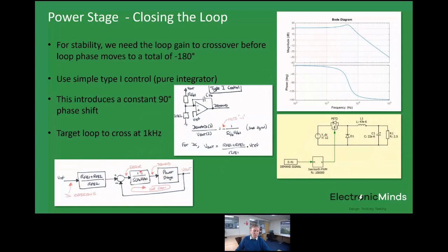We've got this factor of 1 upon S CFB RFB1, and those values relate to the values you can see in the circuit here. But look in the circuit here, when you actually work out this characteristic, there's a negative term here, and that's how this circuit implements the subtraction block for the error amplifier. So really what I'm trying to do is relate that circuit back to a loop gain representation of the whole system here. So that minus is how we implement that error term.